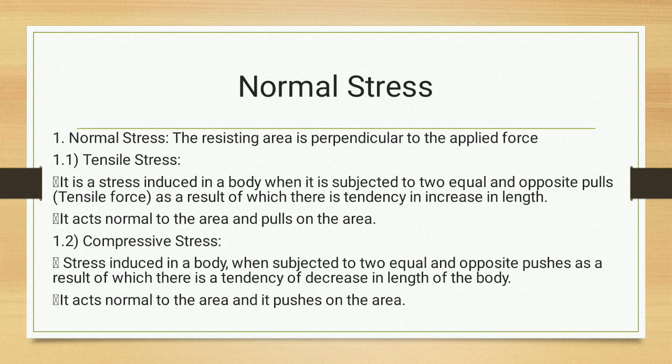Normal stress. The resisting area is perpendicular to the applied force. In the case of normal stress, when you apply the force, the resisting area, the area which resists the force, is perpendicular to that applied force.